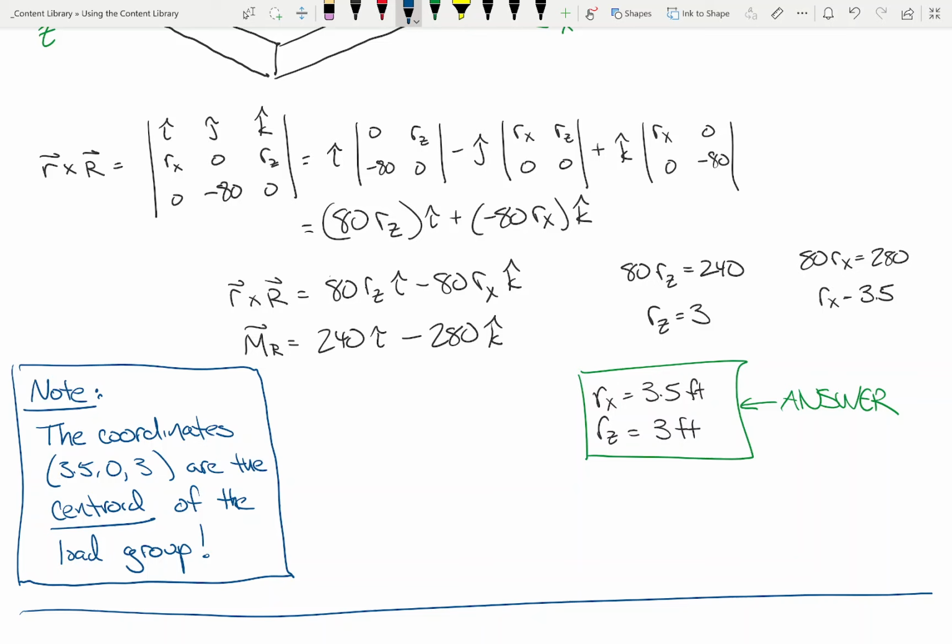Yes? So if you were analyzing that footing or that foundation there, what would you use this for? That's a good question. So if we're fast forwarding into foundation design land, locating where the resultant is as an engineer would help you determine both the capacity of the foundation, but then other things like the stability of the foundation. Is it going to slide? Is it going to overturn? What have you? So the same thing is necessary for both foundations as well as retaining walls. So that's your short answer.